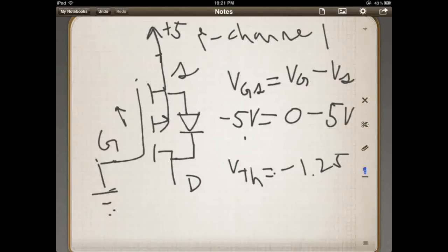Okay, guess we better put volts on everything. Keep your units. Now I have negative 5 volts. Now, negative 5 volts is over that threshold, and so it turns it fully on. So just the reverse. 5 volts turns it off, 0 volts turns it on. So that always helps if you want something that's basically initially on, and then when you give it a high, you're basically just doing reverse logic. These help a lot.